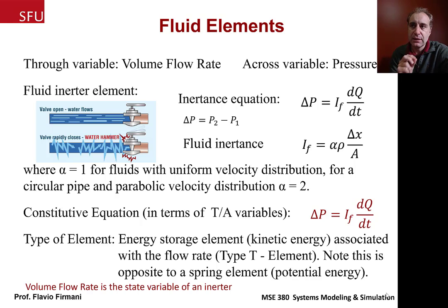Now, water hammer can be dangerous in pipes, and believe me, it can make a very, very loud noise. What happens is that as you change the flow that is passing through the pipe, there is always some air trapped in the pipe, and the water carries inertia. It's going to carry that momentum through its flow.